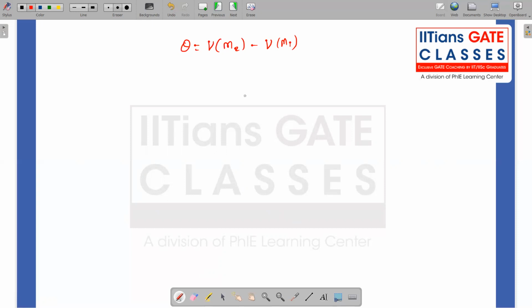Since this functional form is given to you, you can directly put these values in to get the Prandtl-Meyer function. But the thing here is we really don't know what Mach number 1 and Mach number 2 are. How can we calculate that? Again, it's straightforward, because those two are Mach lines. So I can use sine mu1 equal to 1 over M1. From here, M1 is equal to 1 over sine mu1. So mu1 is 37 degrees. If I use that, I should get M1 equal to 1.66.